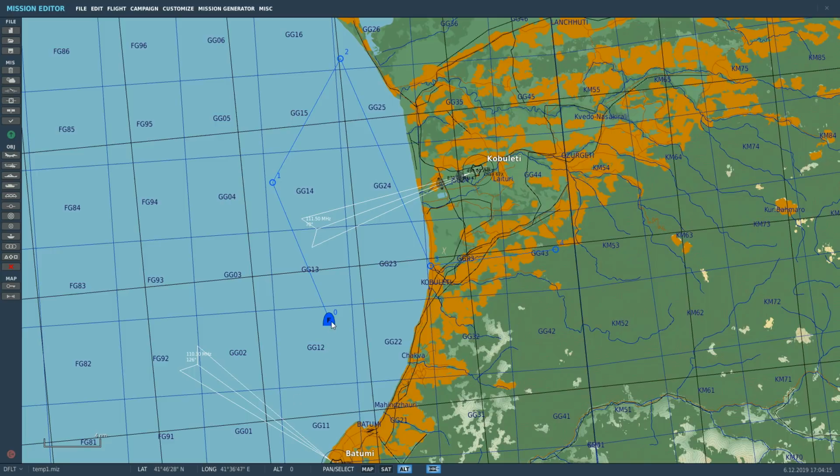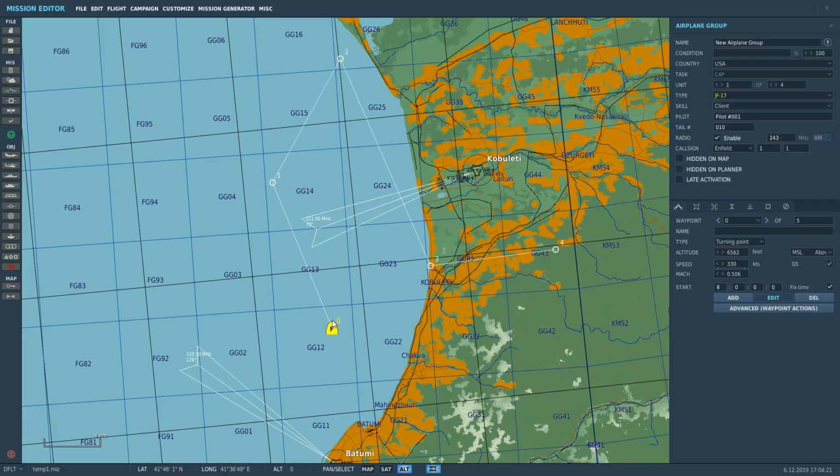The type of waypoints that is used by the JF-17 are three-dimensional instead of two-dimensional. A lot of aircraft in DCS are two-dimensional. We've got our guy here and I've already created waypoint 1, 2, 3 and 4. Waypoint 1, if I click on it there, has a designated altitude in feet and a speed. Notice that as well as an altitude, an X and a Y, it also has an associated speed with it, and all this information will be shown to our pilot via the HUD and whatnot for actually flying the waypoints.